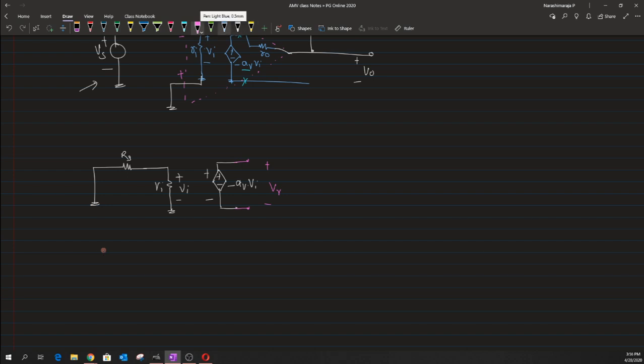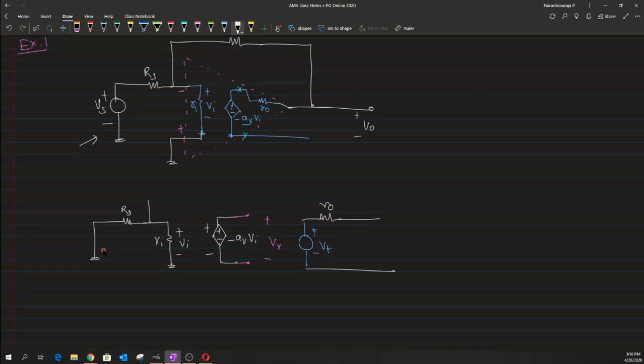Okay, and in the place where we had this voltage controlled dependent source, it has to be replaced with what is known as an independent source. Okay, so let me model this independent source as Vt with the same polarities. Okay, and that's been applied to the rest of the circuit. So we had a resistance R naught, and then we had a feedback from the output V naught to the input side, or basically to the Vi. Yeah. So this is the entire circuit setup that we have, and now we need to find out the ratio of VR by Vt.